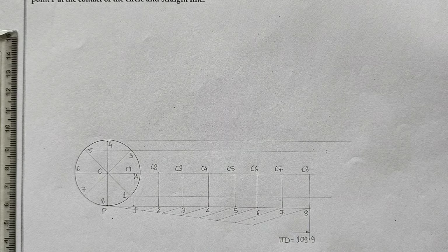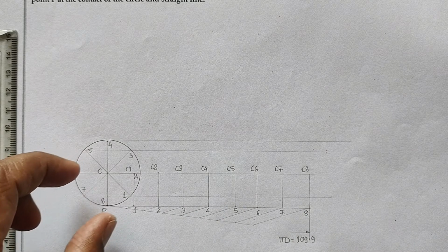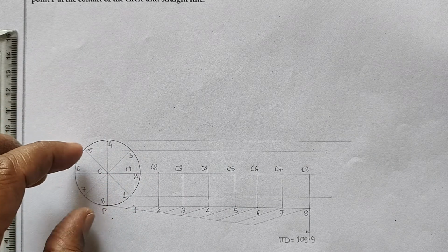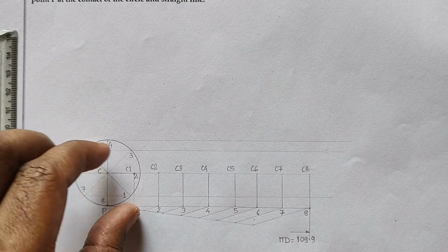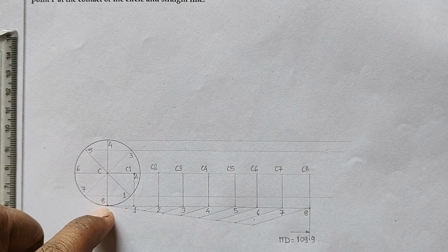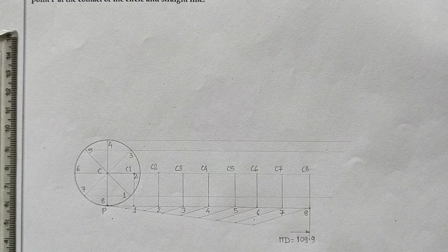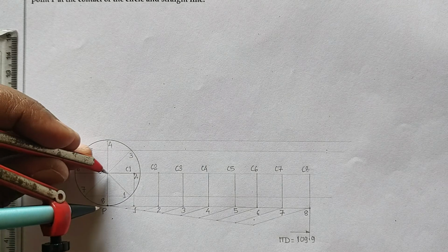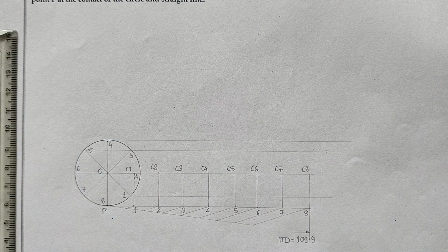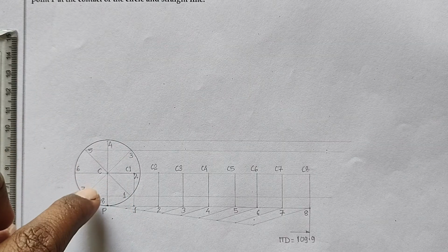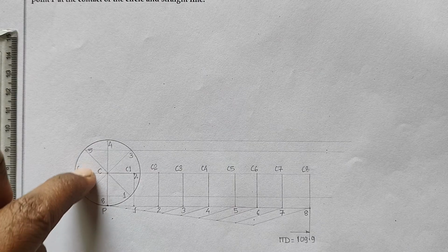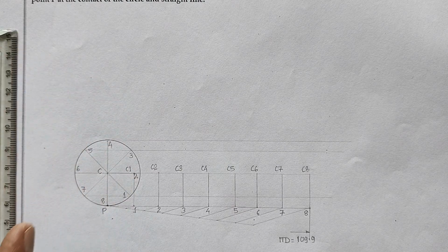Now the next most important work is, when we are rolling this, we have to locate the P position. No doubt one division rolls, that means this one point will coincide with this one point and P will be a little bit lifted. How to mark? Initially the center to P distance is this one. Whenever this circle rolls, the center to P distance remains the same. Only the position of P will be lifted.